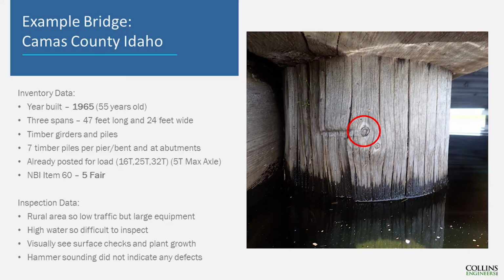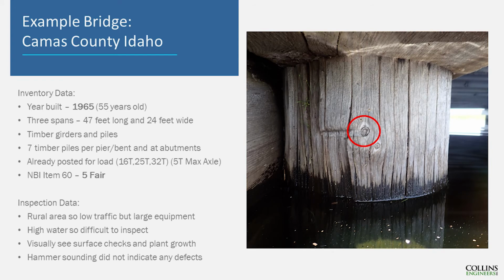It was rated fair. Rural area, so there's not a lot of traffic, but they do have a lot of farm equipment on this one. So you can see some surface weathering, some checks, some surface defects like that. But this pile actually sounded sound from the old traditional hammer test. So we'll see what that graph looks like when I drilled it.